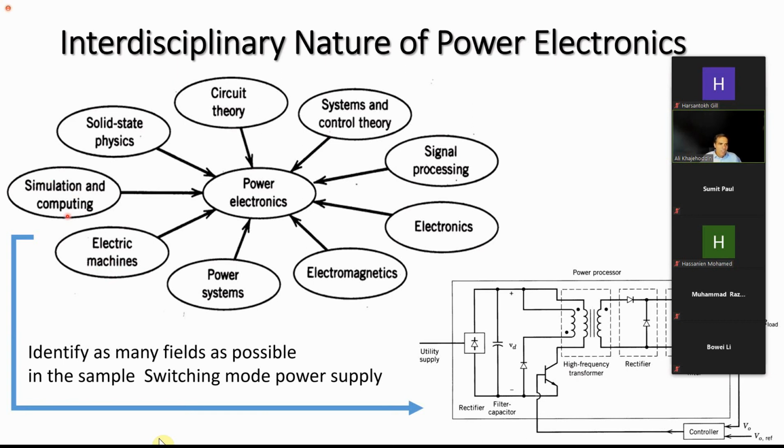Simulation and computing, that's also very, very important. It becomes more important every day as you're trying to push the frequencies higher. For example, in our research group, we're doing megahertz design, and in megahertz design, it becomes very difficult to find the parasitics and calculate them and predict them.